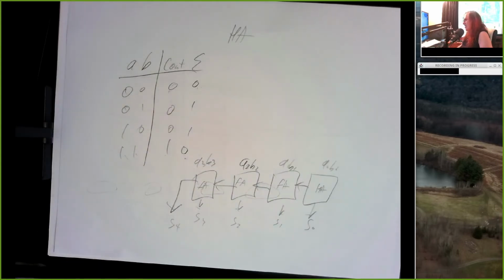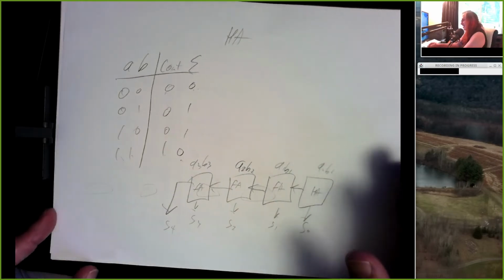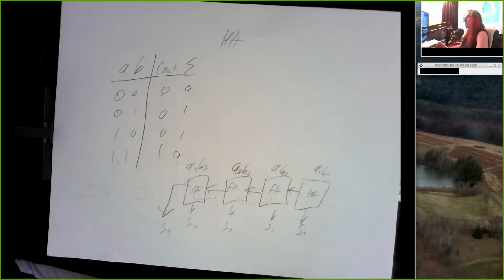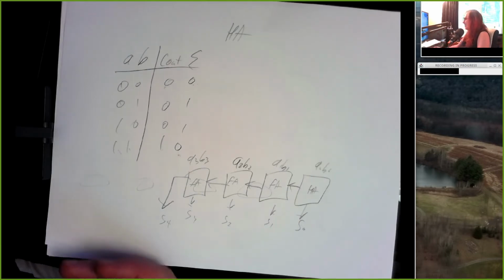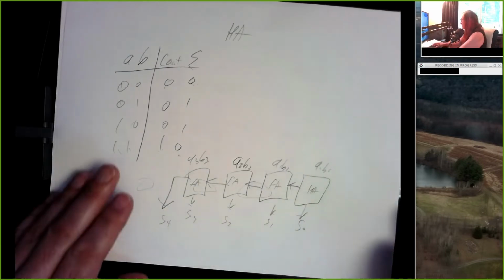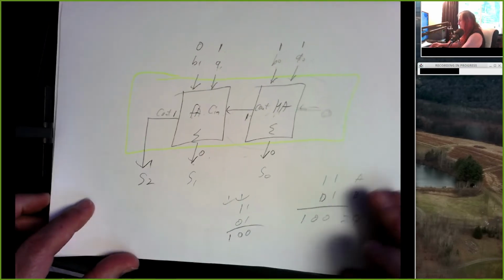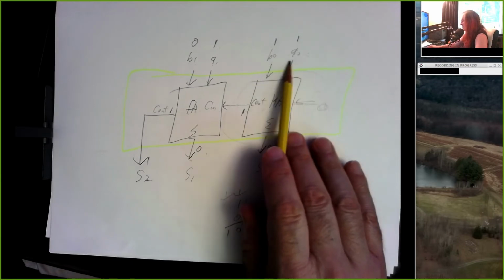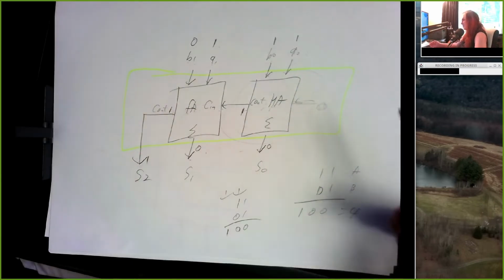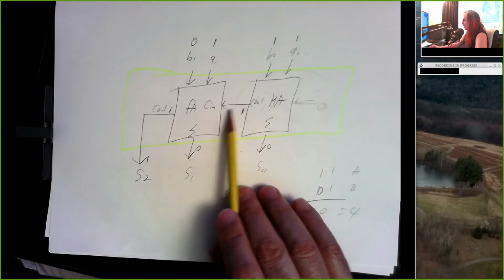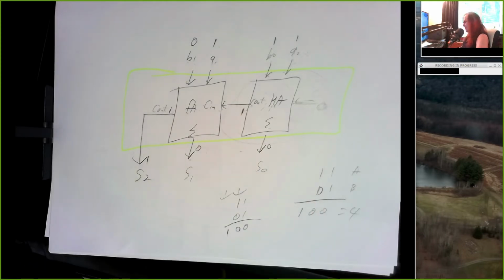Lay those out and try to place them where you think they might be near each other in terms of how you're going to connect them. But you've got wires. But at least kind of decide, do I need one proto board? Do I need two proto boards? Maybe you'll use one proto board for the half adder and one for the full adder, because the connection between these is pretty minimal, right? The least significant bits go here, the most significant bits go here. And we really have one line connecting this carry out to this carry in. So maybe putting each of these on a small proto board would make sense.